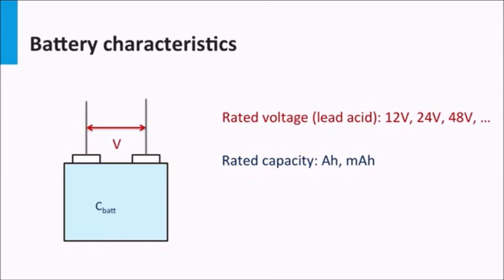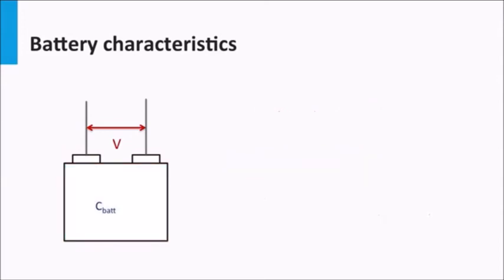It's good to recollect from high school physics that amount of charge is usually measured in coulombs. As the electric current is defined as the rate of flow of electric charge, the charge can also be equivalently measured in ampere hour. Therefore, we can quantify charge in both coulombs or amp hours. But we will stick to the more convenient unit of amp hours for measuring the battery capacity. I will shortly explain the reason for this.